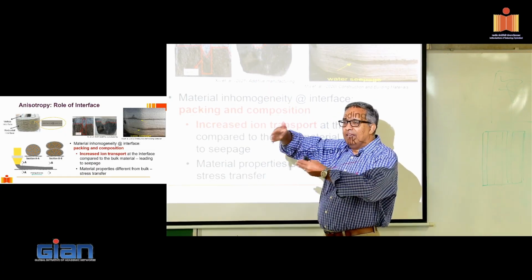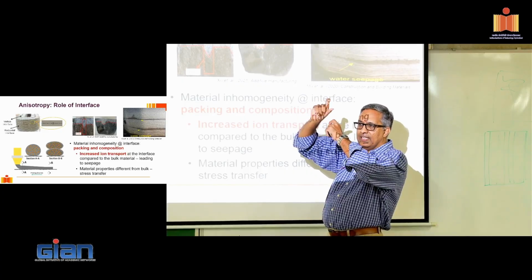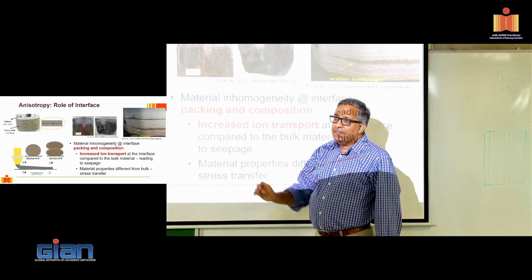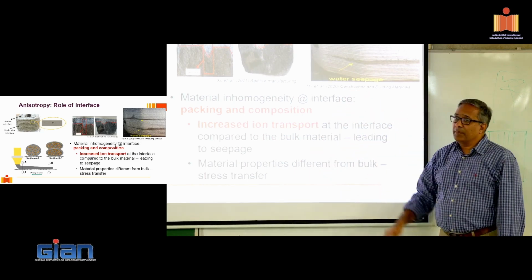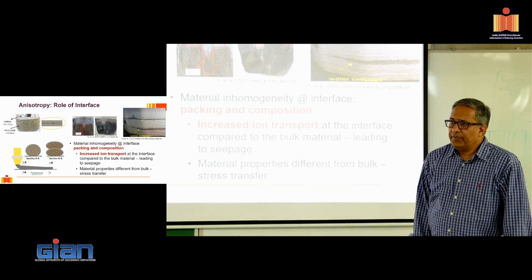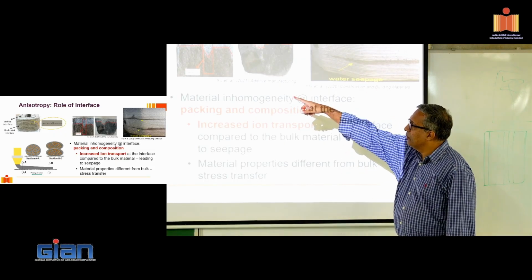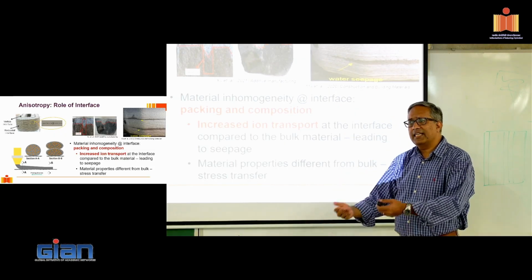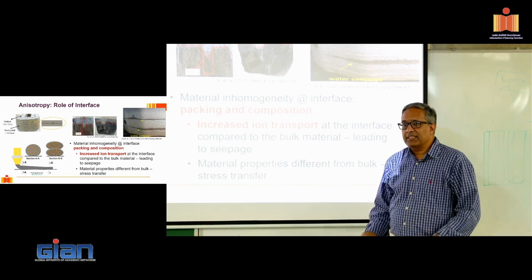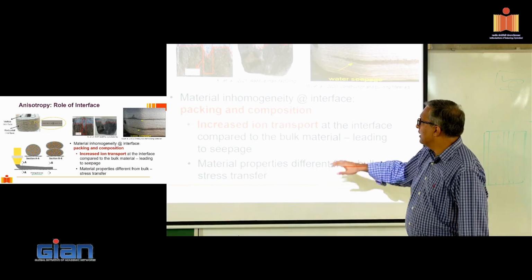Or naturally, as when the two filaments are simply resting against each other, you do get this interface, which does allow a faster penetration of liquids, water. So you'll have seepage if you don't have a proper interface that's formed. Water will get in preferentially. More worrisome for me is that chloride ions and all these other ions can also get into the concrete.